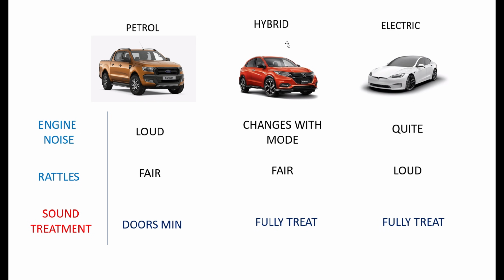Once again, when it's in electric mode, the wind, road, and internal rattles and things become far more detectable than when you're running your petrol engine. It's another reason why you really want to fully sound treat a hybrid car. When I say fully sound treat, I'm talking about the wheel arches, the doors, the trunk, that type of thing. You've got to be careful about sound treating around where the battery storage areas are.